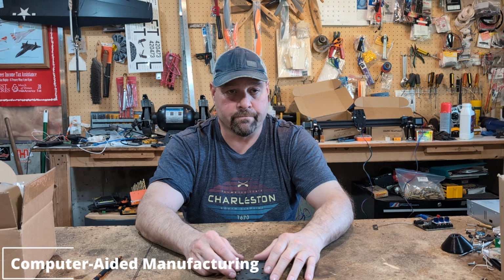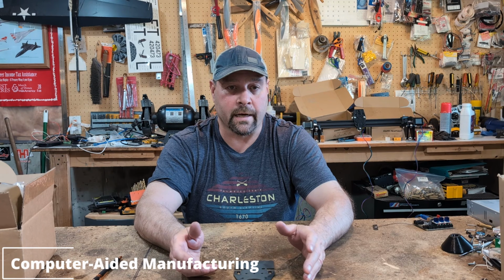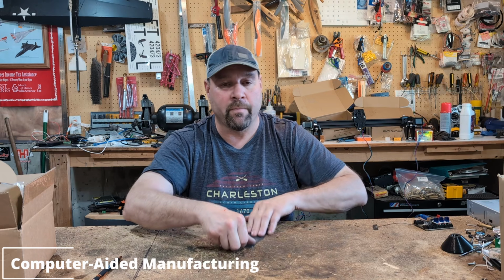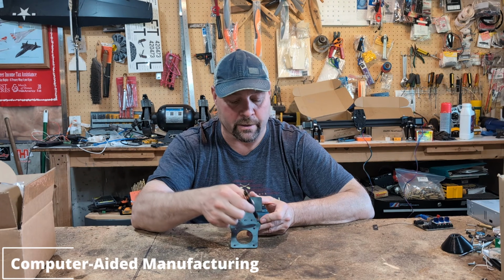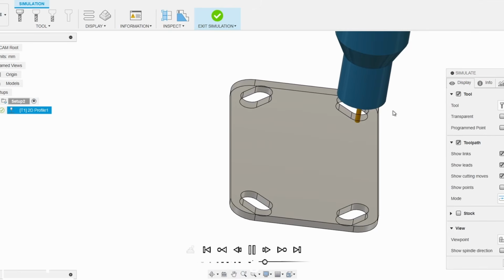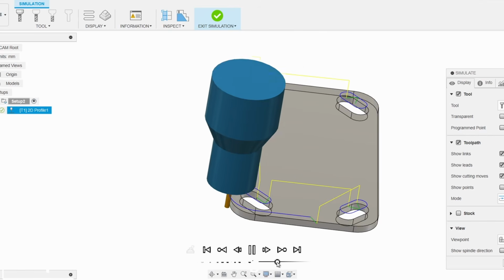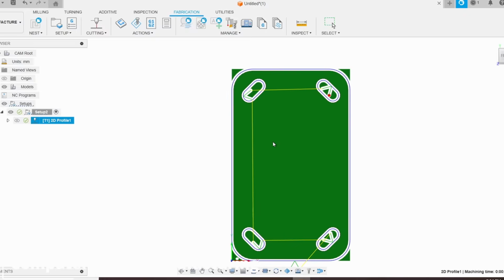So now we've talked about the CAD, we're going to move on to the second software. The second software is the CAM software, or the computer aided manufacturing. So now that we have the part drawn, we have to tell the plasma cutter how to run around these points and how to lift up, move over, go around the circles, how fast to go, everything that the plasma cutter needs. With making the tool pass on that, the last thing that happens is it turns these tool paths into G-code, and you have to have a post processor to do that.